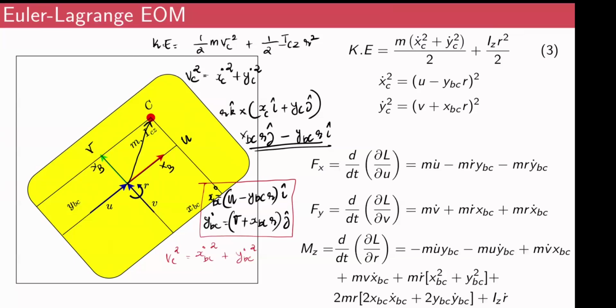But that's not the case for a spatial robot that can move within different planes, or a robotic manipulator which can move in space. But in the case of a planar mobile robot, you can fix the datum as the plane of that mobile robot itself, and due to that, you can consider the potential energy to be zero.